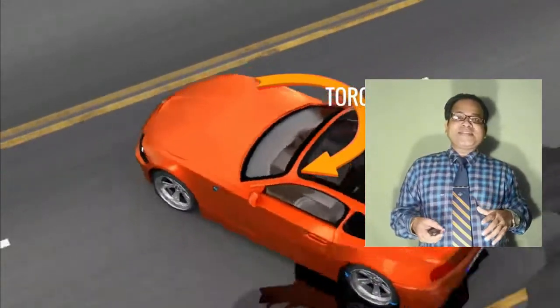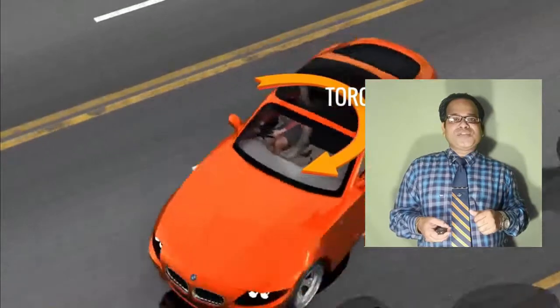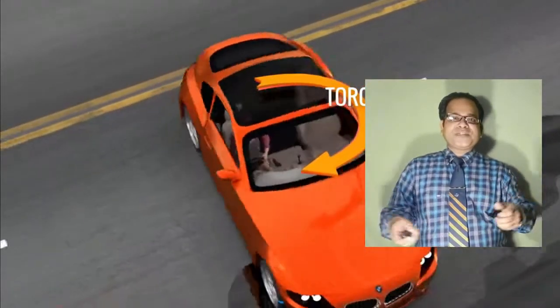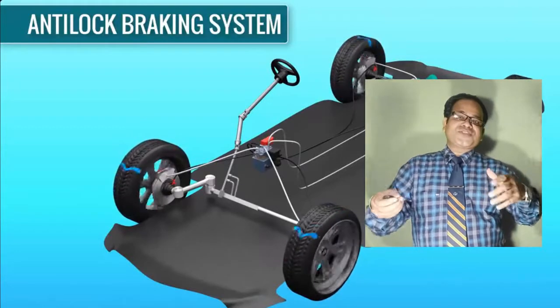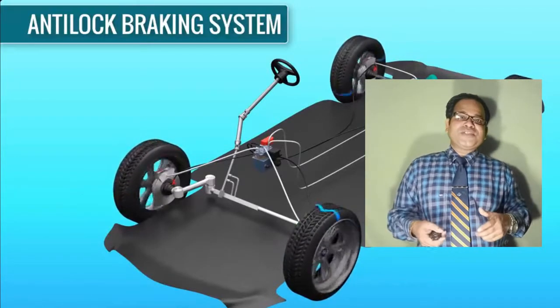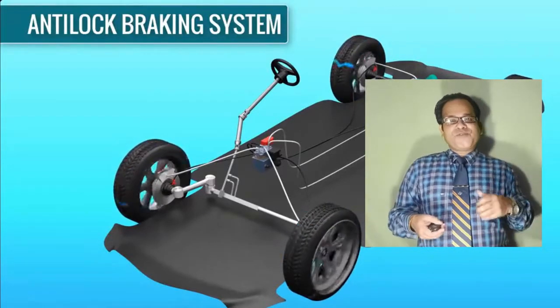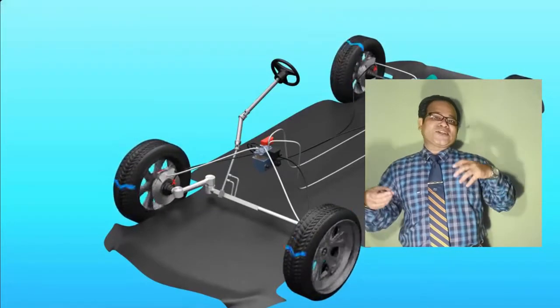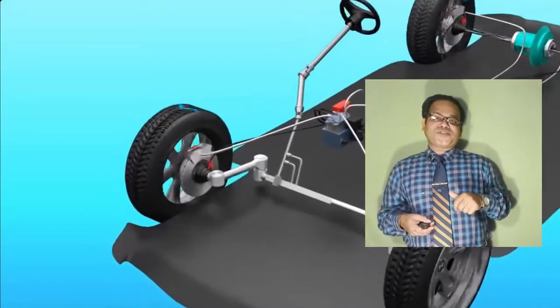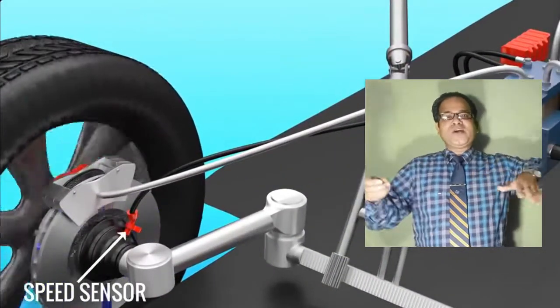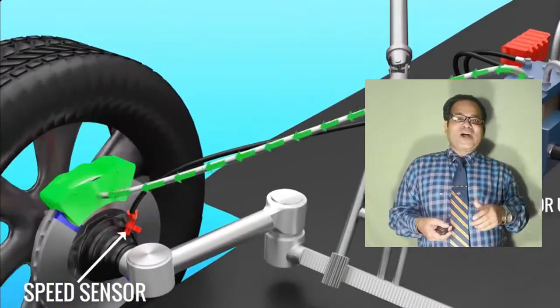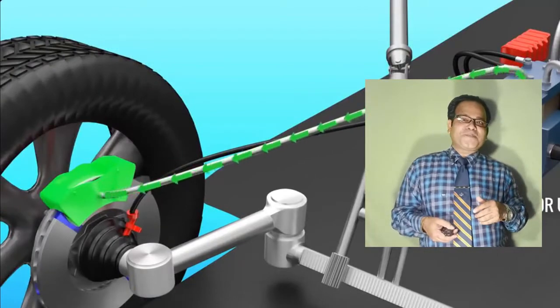Apart from losing control of the steering, if the car is without ABS, there is one more challenge: moving on surfaces having different frictional coefficients, say a greasy or slippery surface under the left and right wheels. The brake will generate a differential frictional force on the wheels, and that causes a huge amount of torque and results in the whole car going into uncontrolled spinning. Let's see how ABS solves this problem.